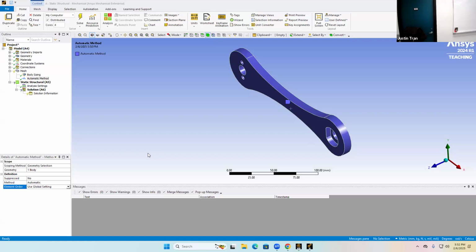So it's under 5 millimeter. Yeah, entire body. Oh, you need to select the geometry for this. So click on, yeah, you're good right there, and click on right here, and then click apply. Every mesh object, you have to assign what part of the object it is.